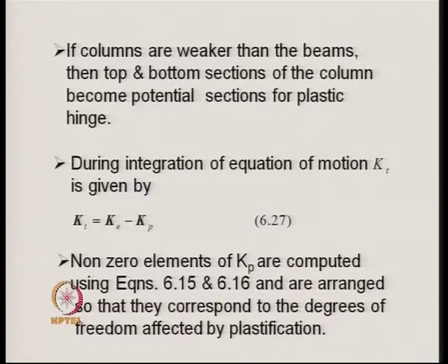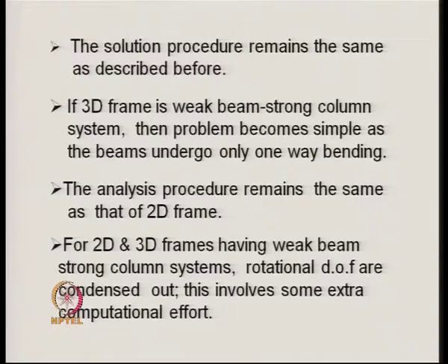Therefore, at the yielded sections, the associated degrees of freedom are arranged accordingly in the entire sequence of degrees of freedom. Then the solution procedure remains exactly the same as described for the single story 3-dimensional frame.